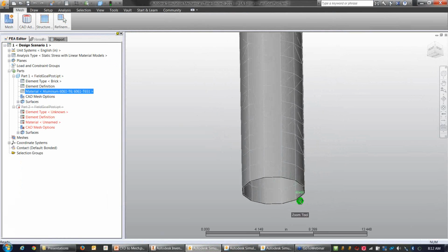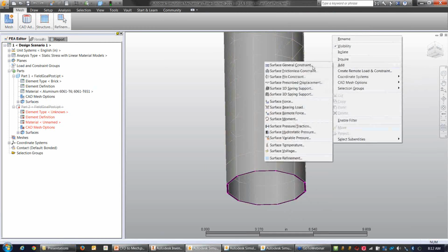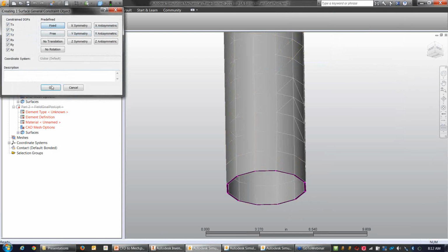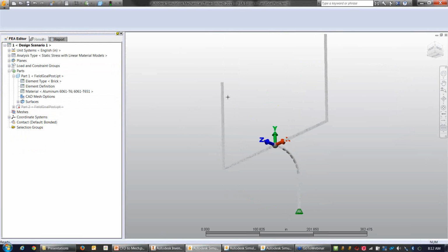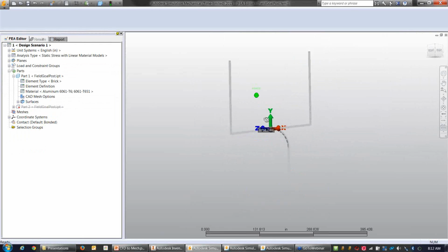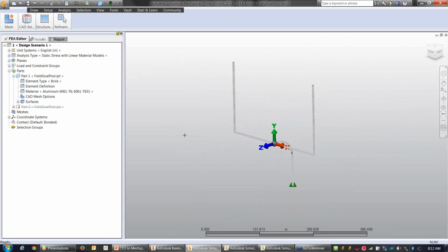May I add something? That looks to be the case, Jim. Basically, it's a non-slip boundary condition anywhere at the interface between fluid and solid. By default, it's a non-slip boundary condition, so the fluid velocity at the surfaces of the goalpost would be 0. All right, so thank you, Marlon.